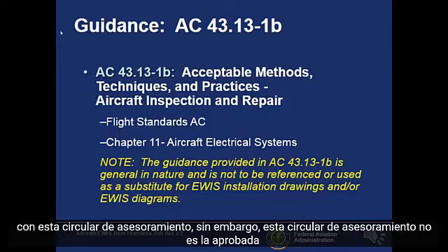If any equipment is added to the aircraft, there needs to be a load analysis. Now typically when we add aircraft components to our aircraft, they come with an STC that has already done the load analysis for us.